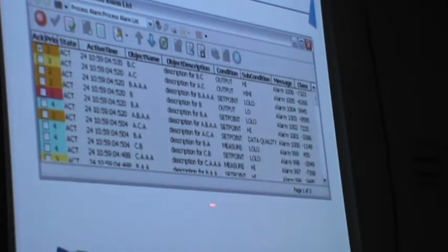So these are the alarm displays. Here you will get the priority. What kind of priority the alarm is, whether it is higher priority or low priority, that will be the number here. For a high priority alarm, if that is the reason for tripping, all will be configured as high priority alarms. You can select the priority here. So if you filter by 1, you will have the most reasonable alarms that can trip the pump. First all the alarms will be in the first one, the higher priority alarms. So you can filter in that manner and check it.